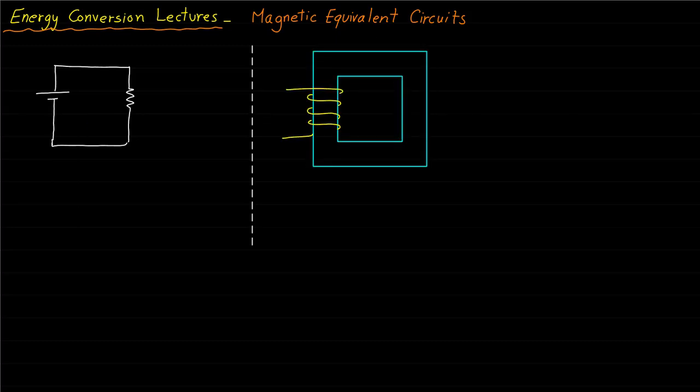The electrical circuit consists of a voltage source E or electromotive force EMF and a resistance R. The EMF produces or drives an electrical current I against the electrical resistance R. The electric current of this electrical circuit can be determined by applying Ohm's law as follows.